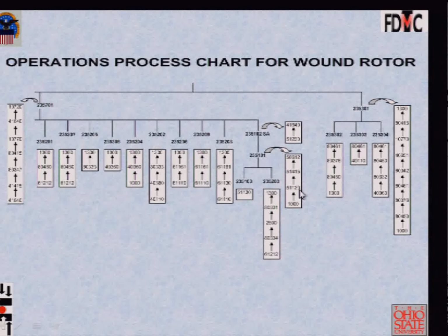And you know that to minimize work in process, that is to minimize the time that this subassembly is not done, you would first try to run this component through this work center and then run this more complicated work center. Now that is SPT. Sometimes the logic would be just the reverse. It may be to run this complicated routing through work center 130 and then run this. The point again is that you can see automatically just at this level, because these 2 components which go into this subassembly are going to have to visit the same work center, there is a scheduling difficulty.